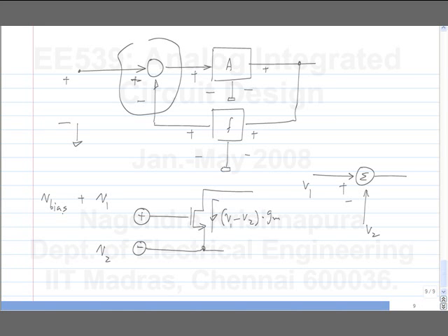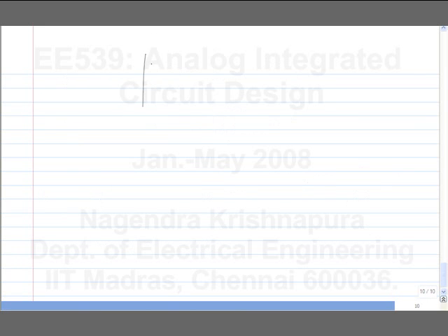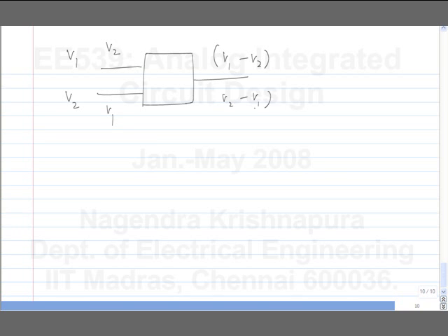Does this circuit look the same from V1 and V2? What I mean is, when I want to take the difference between two voltages, let's say I have V1, V2. Ideally, one of the characteristics I am interested in is that here it is V1 minus V2. I don't care if it's voltage or some current related to this. Now, if I swap V2 and V1, I should get V2 minus V1. You should also keep in mind that the sources that drive V1 and V2 don't have zero output resistance. They are not ideal voltage sources. Will that happen in our case?